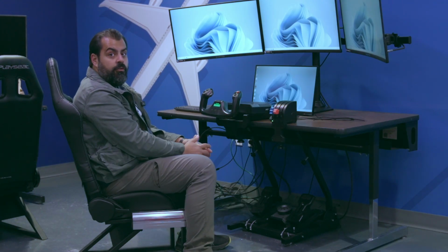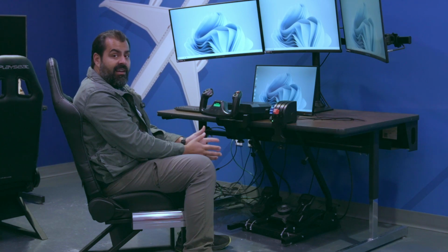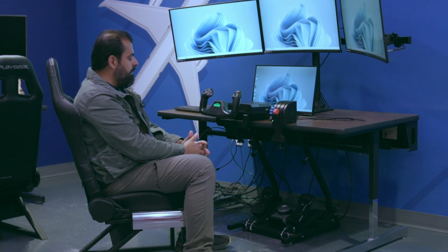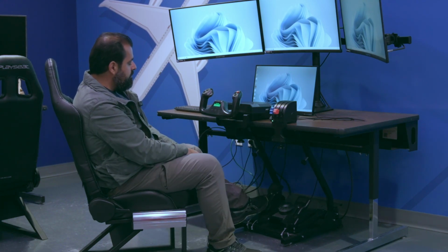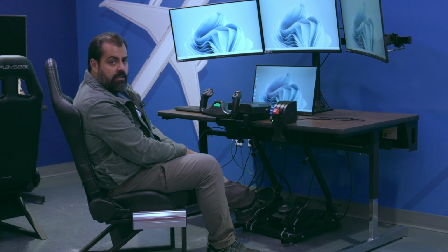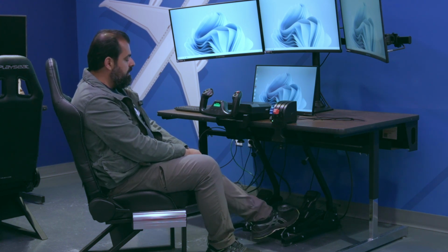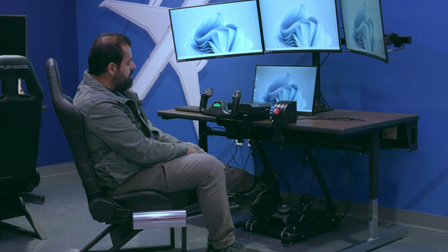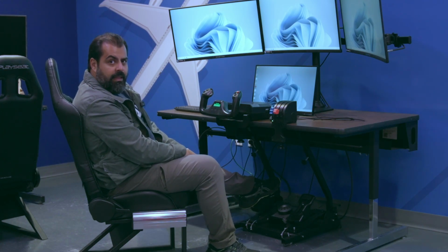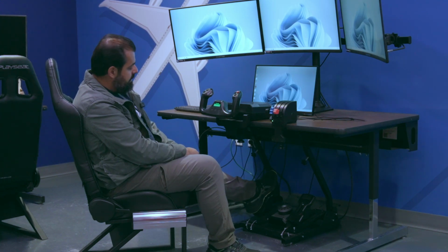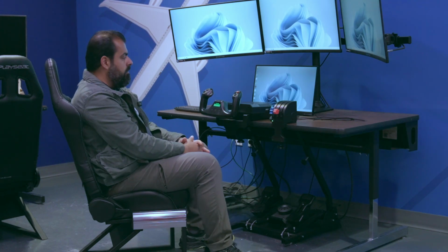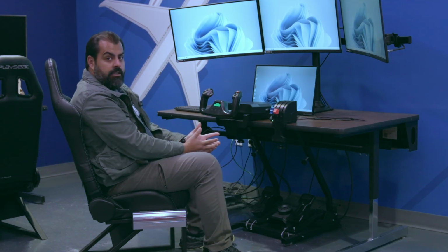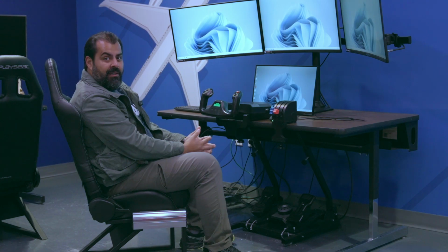The first thing you want to do, of course, is to make sure that these are calibrated well, and we are going to do that in a second. The next primary flight control we have are these pedals, the rudder controls. Essentially, they do a slide. If you use the left slider, it will turn left. If you use the right slider, it will turn right. And if you press the top of it, that will activate or deactivate the brakes, like you would do in a car. Just press the top of it. These are the only primary flight controls we need to worry about.